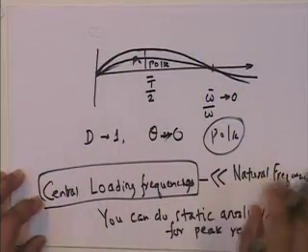Once you do that, if those are very small compared to the natural frequency of the structure, you have a very rigid structure. If you have a very rigid structure, any loading is going to be a static load for the rigid structure. So, in other words, you do not need to do dynamic analysis at all. You can just do static analysis and get away with it. Is that clear? Okay. So, that is the beauty of this approach.